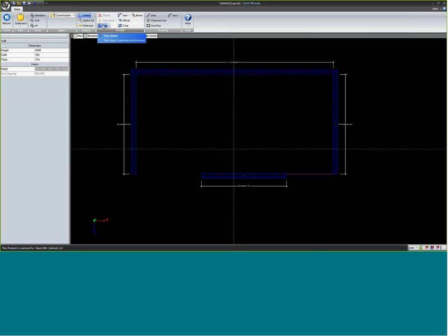There's lots of other tools here. We won't cover very much of them, but offset lines, you can move that line. You can join used for putting a fillet or a chamfer on the edge of a line. Bend is just what it sounds like. Trim, if you have two lines intersecting, you can trim the tail sticking out the other end. Transform, you can rotate or mirror different lines. Crop will crop everything outside of the box I draw, like that. So you can play around with these a little bit and get more use of them.